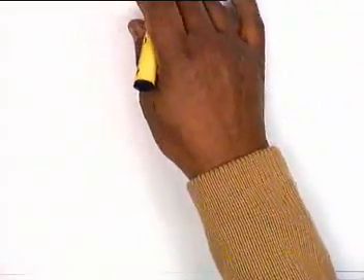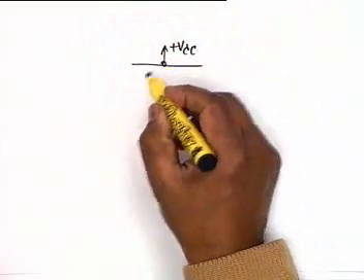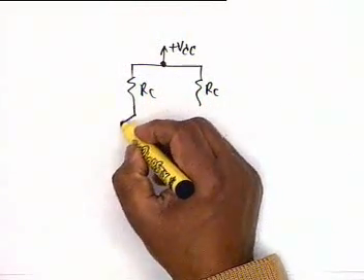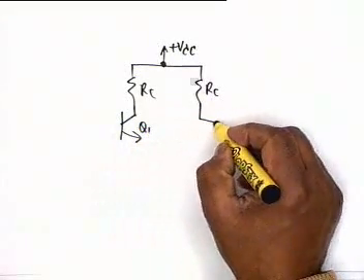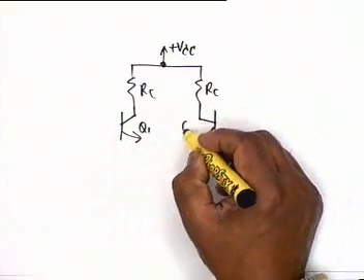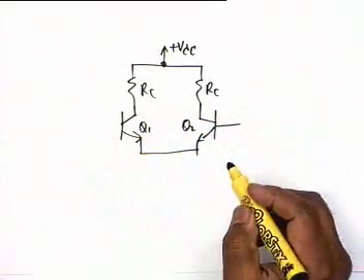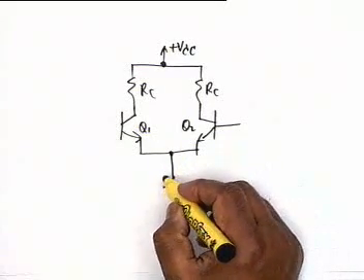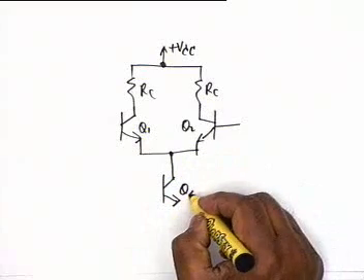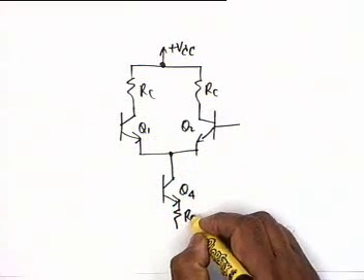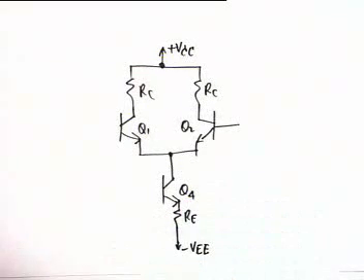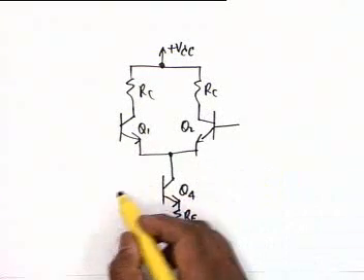All right. So our circuit, how RE is used, is like this. We'll draw it quickly. R sub C, R sub C, then we have the two main transistors Q1 and Q2. These are connected together. This is supposed to go to REE. Instead, what we do is we take it to a transistor, let us say Q4, with RE. This goes to minus VEE. This is the main transistor of the current mirror and this is that Widlar resistance RE.